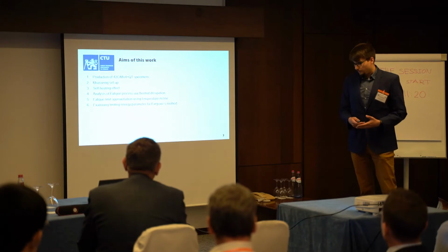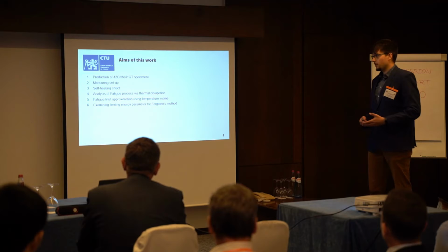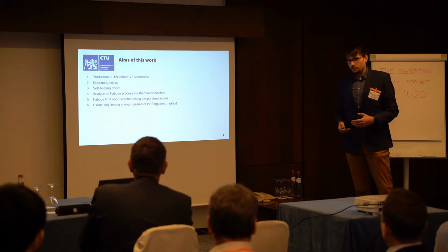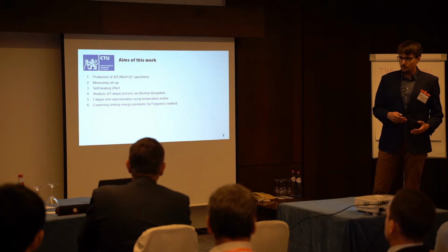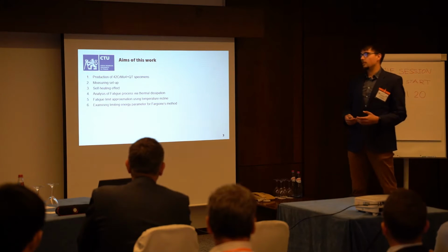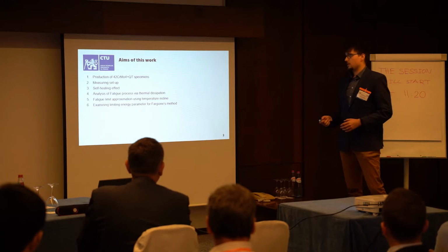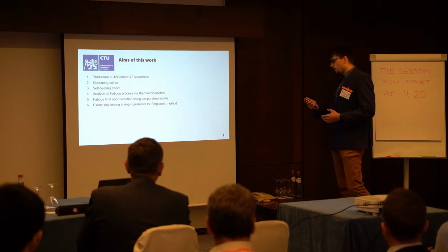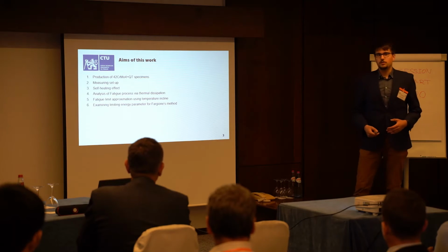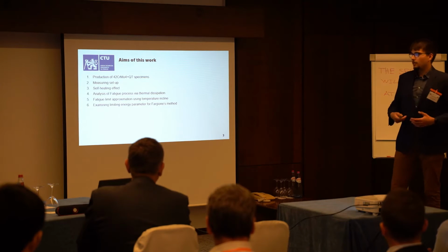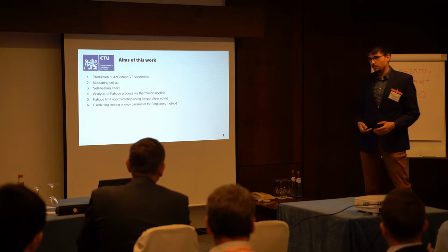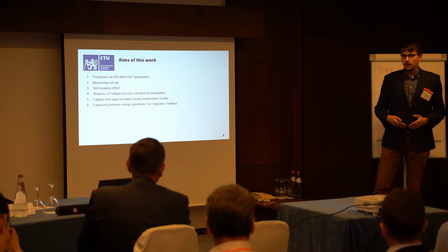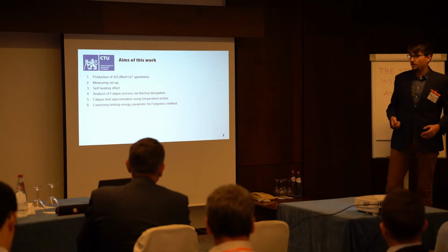So briefly, this is the outline of my presentation. I will say a little bit about the production of the specimen, then the measuring setup which we are using, the key factor in this presentation, the self-heating effect, and all the motivation behind it. So first of all, the motivation behind this is to speed up the creation of the S-N curve using the temperature evolution instead of doing the S-N curve as a standard, as it's done normally.